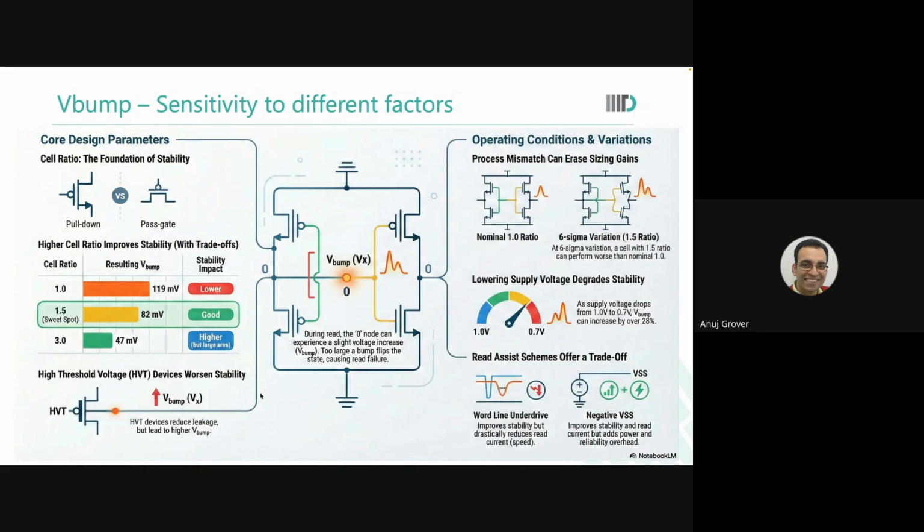Now, if all the arrays are going to operate at a higher supply, it may be worth putting a small voltage regulator, not a charge pump, a small voltage regulator somewhere in the chip. Interestingly, the array doesn't consume any power. What power does the array consume? Nothing. See, bitline pre-charge power comes from the IO. The array only charges up the internal node of the memory cells where something needs to go to 1. Look at the array supply. Where is it used? Only that place. Otherwise, it is only leaking. It is only there to maintain whatever the contents were.